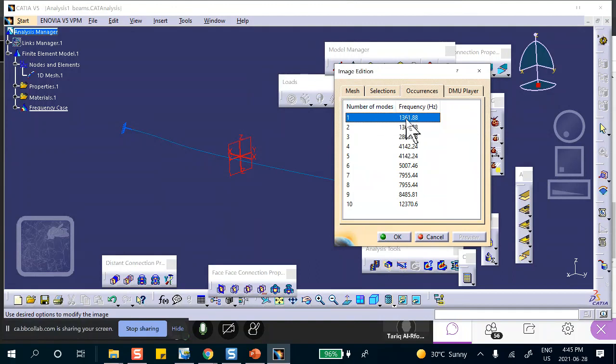Okay, and if you say, well, wait a minute, this is quite a bit off. Well, first of all, I have absolutely no confidence in my original number, 866. I told you. Second thing is that what I did here, clamping here, this is not the same clamp as I clamped there, because there it assumed that that edge at the end where you clamp cannot change length. There is no such assumption in beam bending.